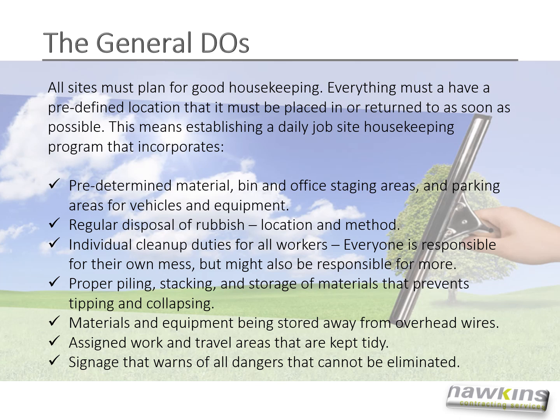Regular disposal of rubbish, meaning the location and the method. Individual cleanup duties for all workers, meaning everyone is responsible for their own mess, but might also be responsible for more. Proper piling, stacking, and storage of materials that prevents tipping and collapsing.